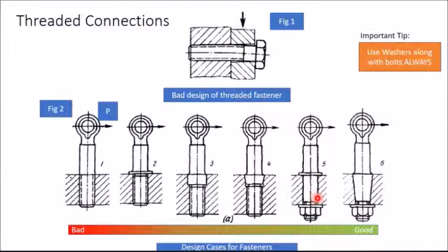They have a cylindrical or tapered section fitting in the housing. In this case, the internal threading is provided by the nut instead of the housing, and so the threads are completely relieved from bending and take up only the tightening tension.